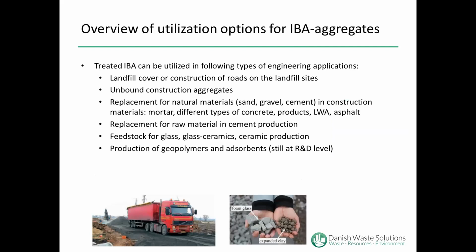So what are the utilization options for bottom ash aggregates? Let's now assume that we have a bottom ash which has been treated, meaning the metals have been removed and the material has been stabilized to some degree. And we have different options what to do with the material. The most common one would be construction of landfills or landfill cover.